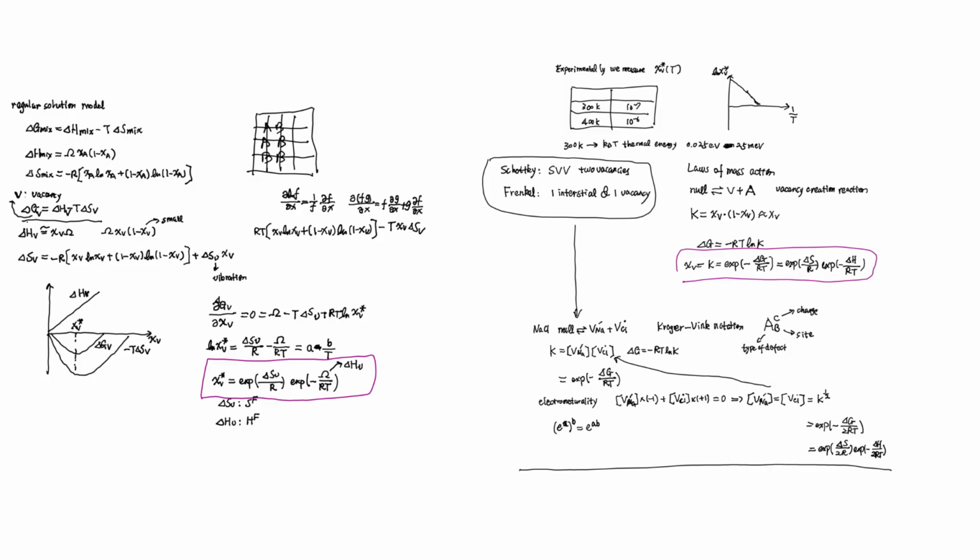Because silver is supposed to be much bigger than lithium or sodium. So why does it want to form the interstitial instead of a vacant site? It's counterintuitive, because silver actually is quite small in the ionic crystal. So that's why it wants to form the Frenkel defects.